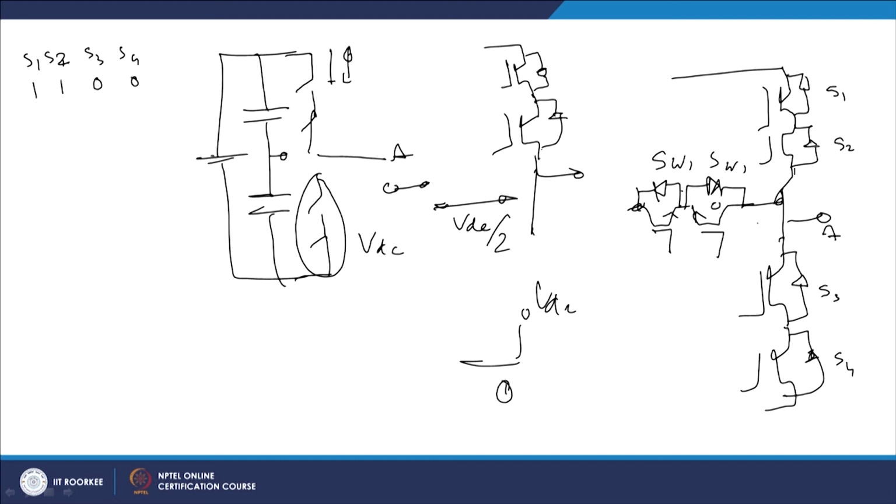Same way, if you wish to connect, there is a redundancy. Where you can connect, because you have a capacitor midpoint. So, this point will be connected here. You can find that if you connect a diode simply through this point, it can work anyway.